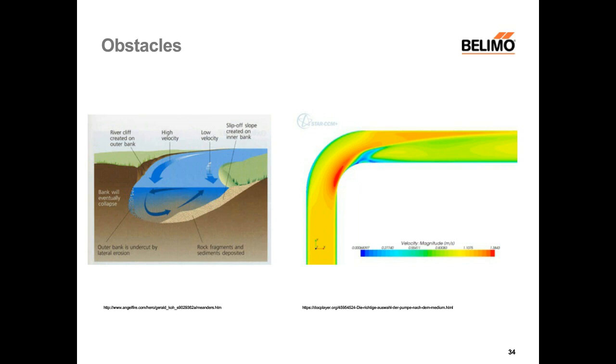This is why we recommend some straight inlet length before a sensor. You will just measure more accurately. And in this respect, inline sensors with a known geometry of the flow body can also influence the flow profile in a positive way and better adjust to the flow situation.